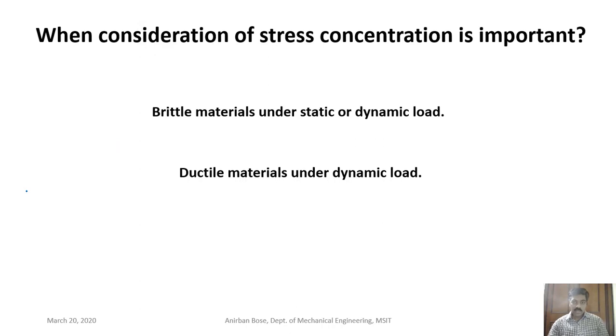Now let us see how materials behave under stress concentration. So when is consideration of stress concentration important? Is it important for all kinds of material, ductile or brittle? The answer is that in the case of ductile material, if it is under static load, then it is not so important. If the material is ductile and the loading is static, then stress concentration consideration is not so important.